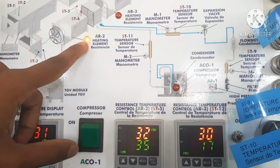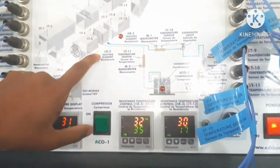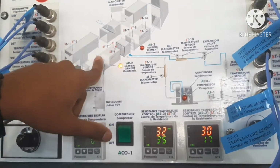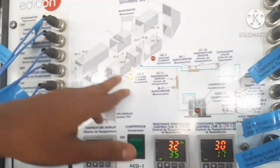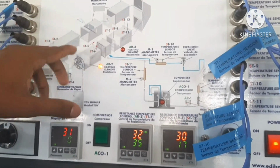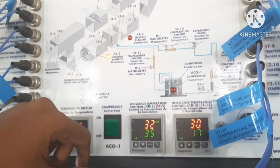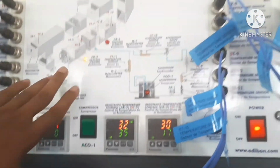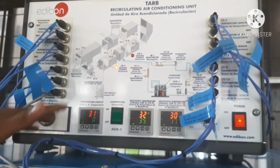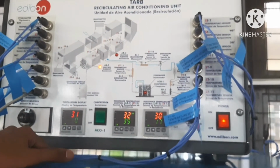This display is for the left side heater. The other one is now off. You can see that the bulb is not blinking, therefore that one is not working. Only this heater is working now, and it will heat the airflow up to 35 degrees Celsius. If you want to measure the humidity change across the heater, we have to measure the temperature inside and outside, two different temperatures of the airflow, dry bulb and wet bulb. Then we can directly calculate the change of humidity before and after the heater. That's how we change the humidity of the airflow.